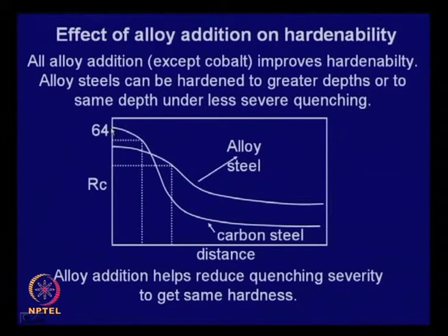This is around a 0.6% carbon steel with no other alloy element, primarily carbon, so it will be a shallow hardening steel, and this is the Jominy hardness profile. Whereas if you have a steel with alloy content, where carbon content is lower, its depth of hardness is much more.